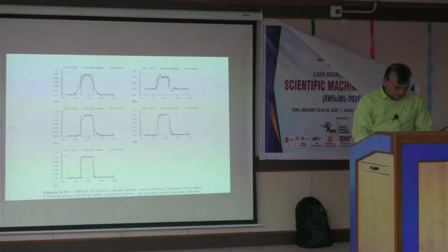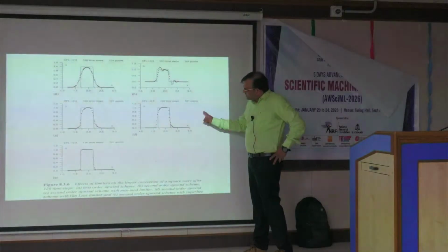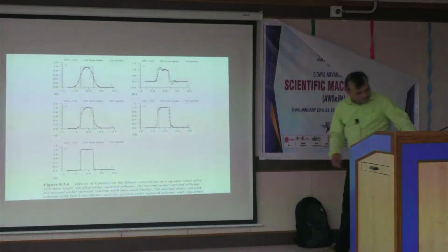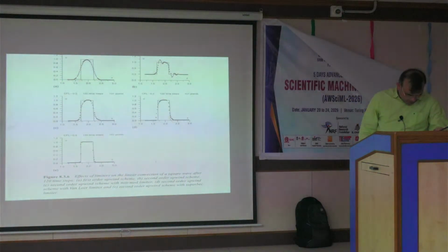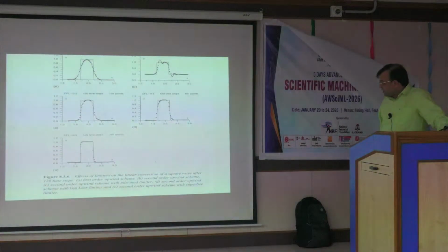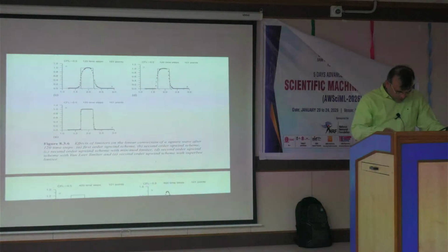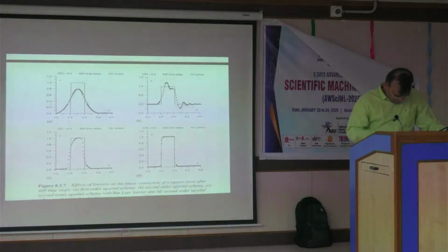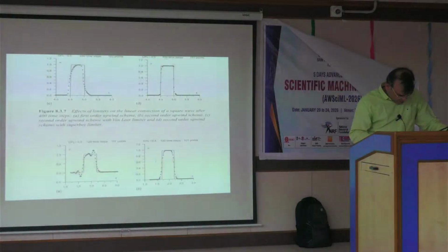Even for the discontinuous data, you can see as you are changing the limiters: second order affine scheme with the minmod limiter which is C, second order affine scheme with the Van Leer limiter which is D, and another one is the Superbee limiter which is E. As long as you are changing the limiters, you can see the solution structures are really nice, by constructing a suitable function.